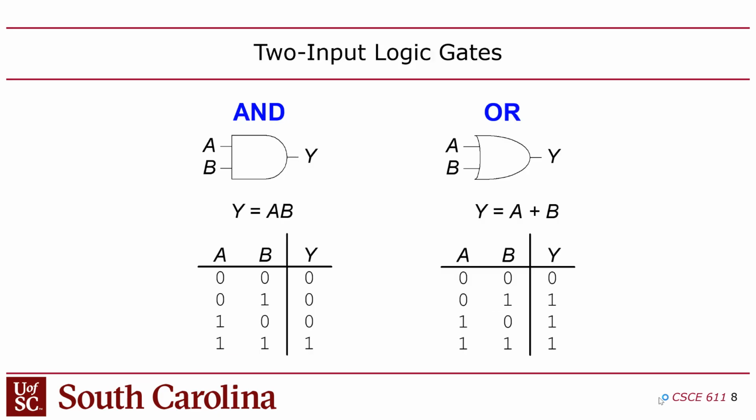And then you had the AND gate and the OR gate. AND gate has 2 inputs and 1 output, and the OR gate has 2 inputs and 1 output, but they have 2 different truth tables. So now notice that you have an output, and that output might connect to multiple inputs of other gates, right? But it's important that you never short 2 outputs together.